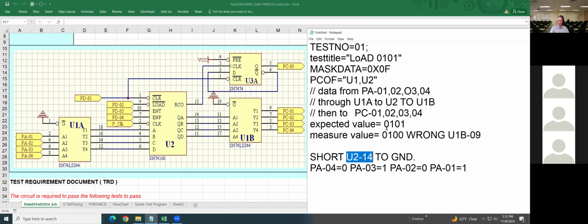So then, this is all in hindsight, but you've got to go backwards to U1 pin 11 and see if you got the same input. In other words, you got an output on U1 pin 9 and you want to see if you got that same value at U1 pin 11. Then, depending on what you get, you go back to 14. Then you go back to 3. You're working backwards. That's what I want to talk to you about.